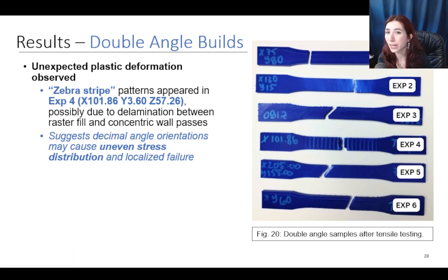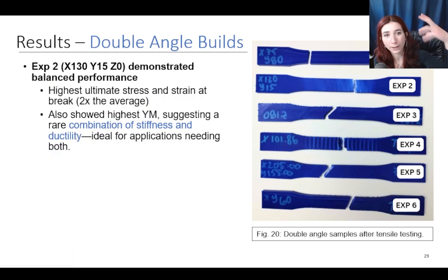We explored this out of curiosity, and in the real world you might not be typing decimal build angles when you're orienting your part, but the CAD data of your part might include different angled geometries, parts branching off, which when you print in layers and apply load, might perform similarly to how some of these build angle tensile tests would.